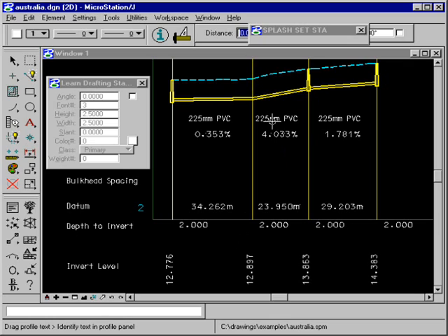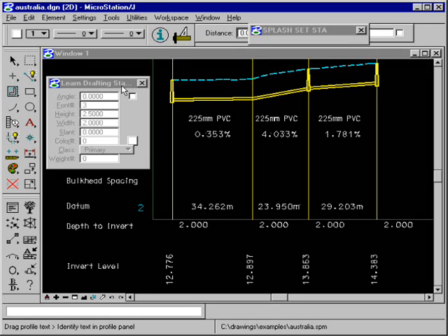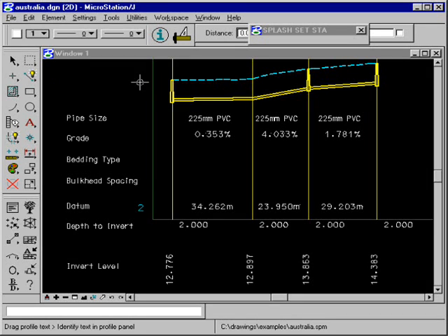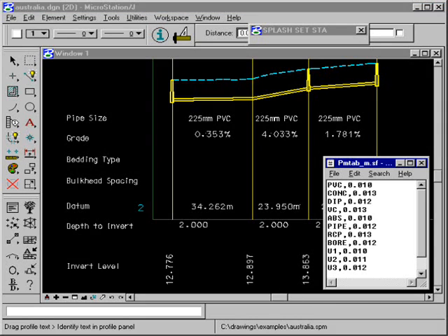Now, this is a little side issue, but it's probably going to occur. This customer has a pipe material called UPVC that's not one of the default materials for Splash. So if we go to the engineering configuration Splash config directory to pipe material, there's a pipe material table and a pipe material table for metrics.